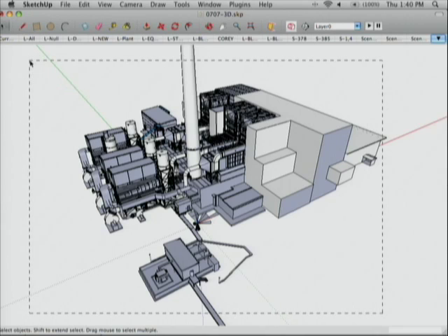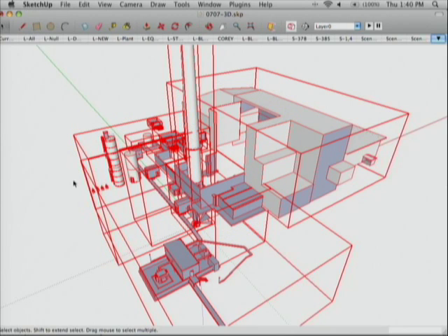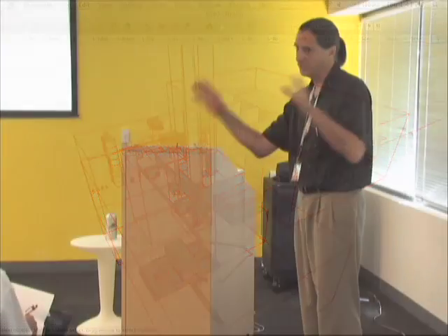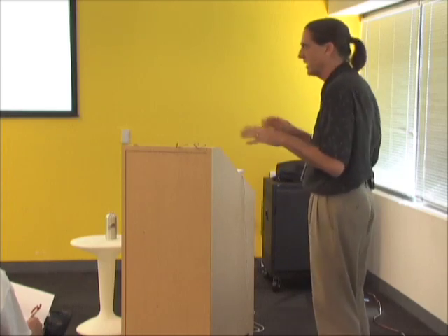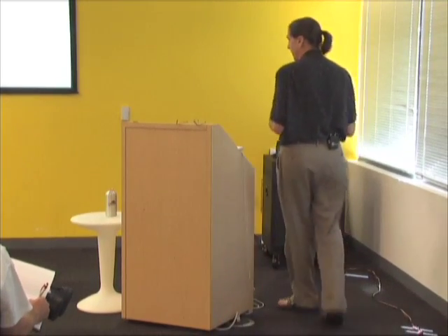So if I come in here and select all my geometry, I hit hide, and anything that's not locked goes away. Hiding is a really good tool. You're working and you've got a lot of stuff in your way. I'm always putting 100 pounds of stuff in a 1 pound bag. So everything around me is always existing. If that's all grouped in a way that I can just touch it and hide it, it all goes away. It's a really simple concept, but if you use it effectively, it can make your modeling go really quick. The display will work quite rapidly with everything hidden.